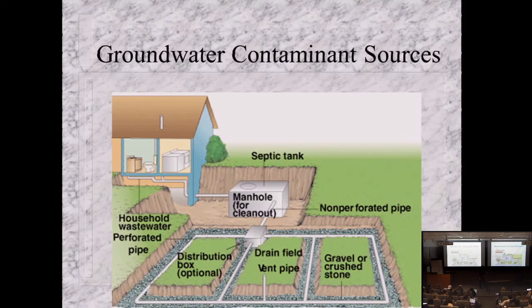Sometimes, though, in the spring, water levels are really high, and so then you're ending up with your sewage going right into groundwater, and if it hits groundwater, it's not going to go away because groundwater is anoxic. There's no oxygen in groundwater, and so there's nothing to break it down. So you want to make sure you have this 5 feet of unsaturated zone. The grass always grows really greenly beneath the septic system. And again, when properly functioning, they work well.